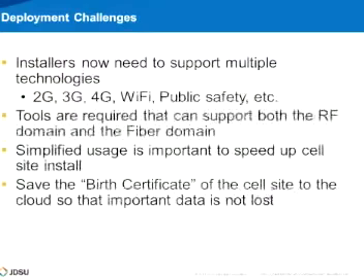To continue on deployment challenges, you'll also find installers now need to support multiple technologies, whether it be legacy 2G, 3G, but also Wi-Fi and even public safety. We've heard that there are municipalities which are actually putting into their building code requirements, over a certain size of building, that if you're installing a DAS system, you must also include public safety bands for emergency responders.